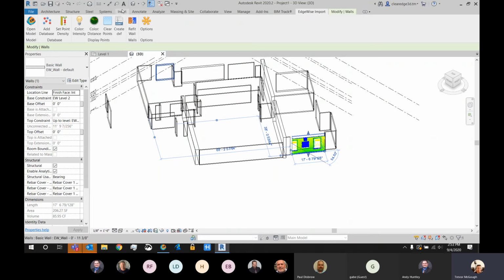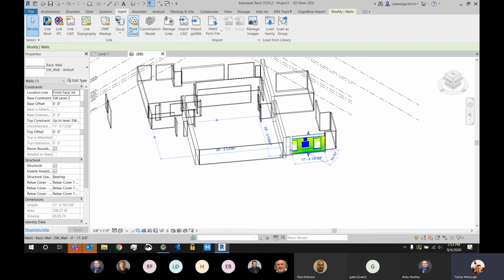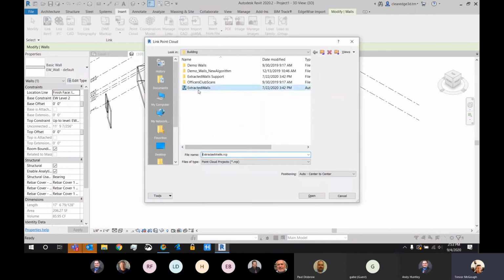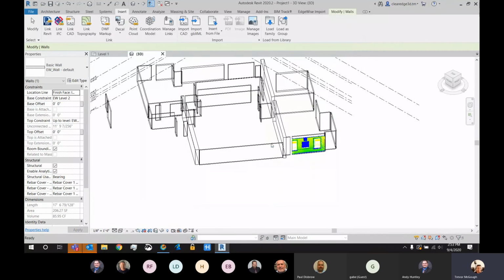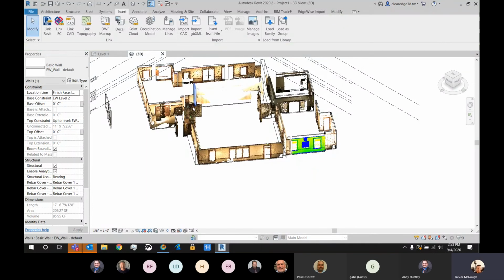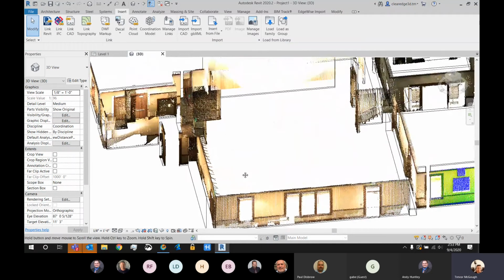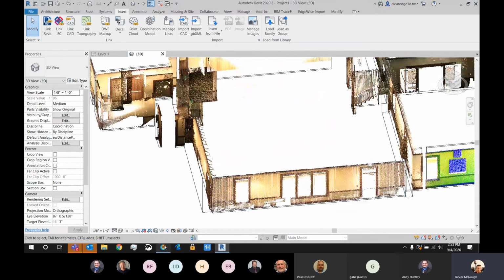Lastly, coming back to that smart points export, I can use those smart points export out with my walls. That actually will be popped out as a Recap project. So if I brought that in, it would look something approximating like this. So there you can see is just the point cloud data immediately belonging to those walls. And this is a very powerful tool that helps facilitate modeling my openings, such as windows and doors. So at this point, as I've said previously, I can save it out.